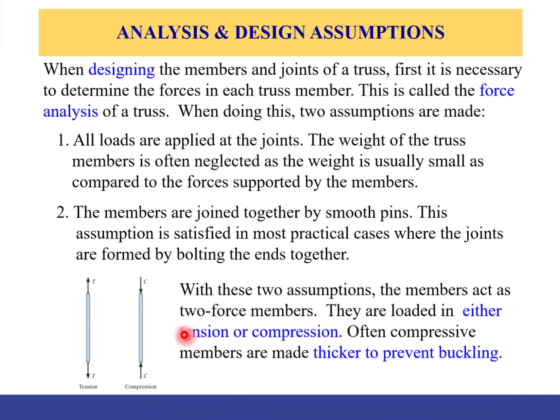In other words, the beam should have either tension or compression as a result of these two reaction forces on each pin. Now, the tension which is along the member must be constant at every section. So the net force here is the same as the net force here, so the tension here is the same as the tension here, or the compression here is the same as the compression here.